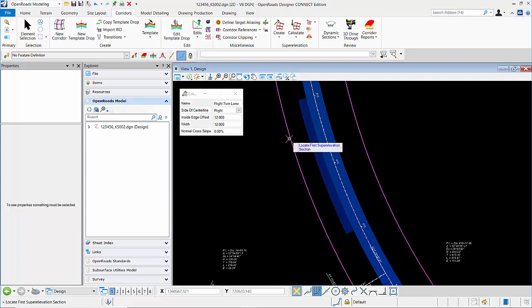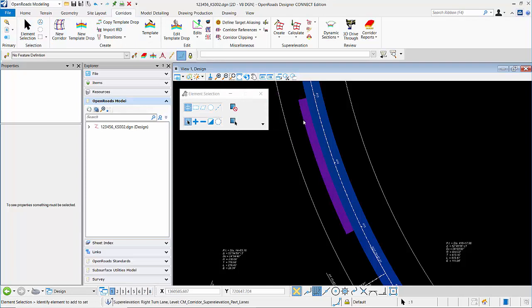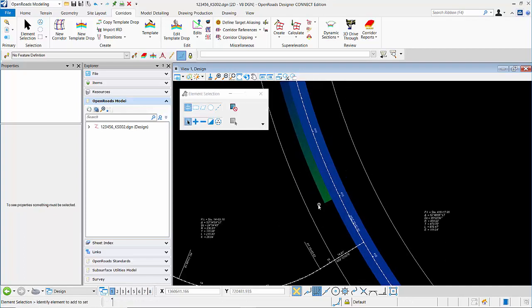So that defines that lane. And if I select that, I can review its parameters, and I can change this slope at this end to 3%. So I can see now some shading as it changes its slope, and I can see the 8% here and 3% there. So I'm going to go ahead and put in another shape.